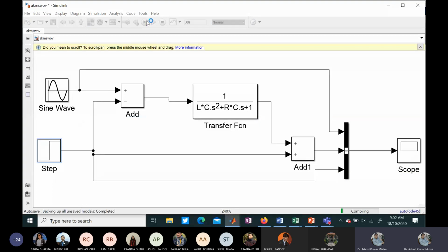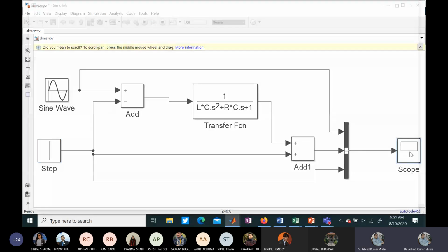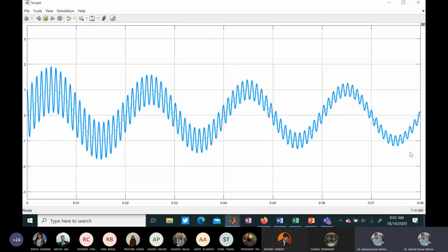Then what is going to be the result? If you see it, this is the sine wave, as you can see, passing through 0, but now the transient over voltage is very near to twice that, 2 per unit, right? So this is the case when we have the switching at the 0 instant and a trap charge of positive peak.